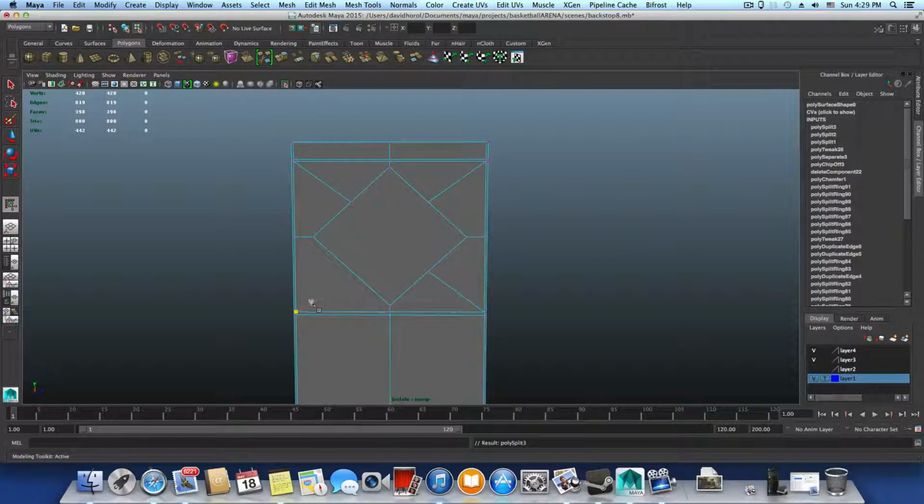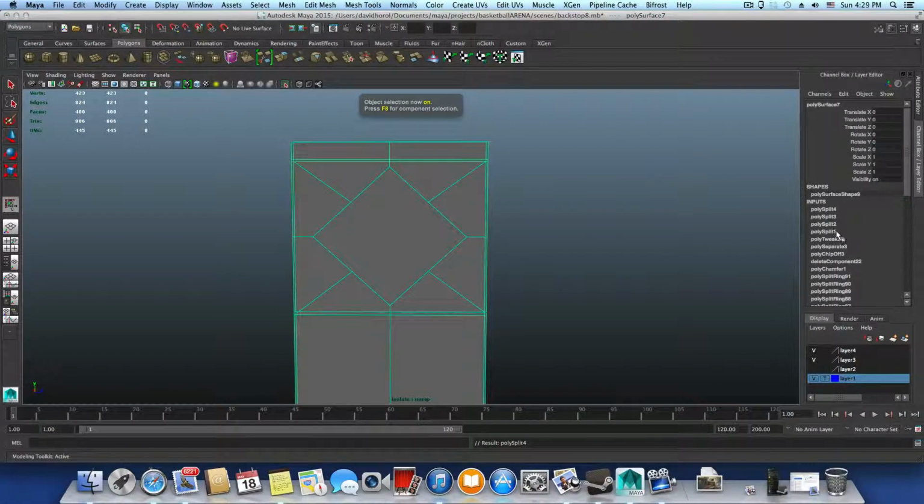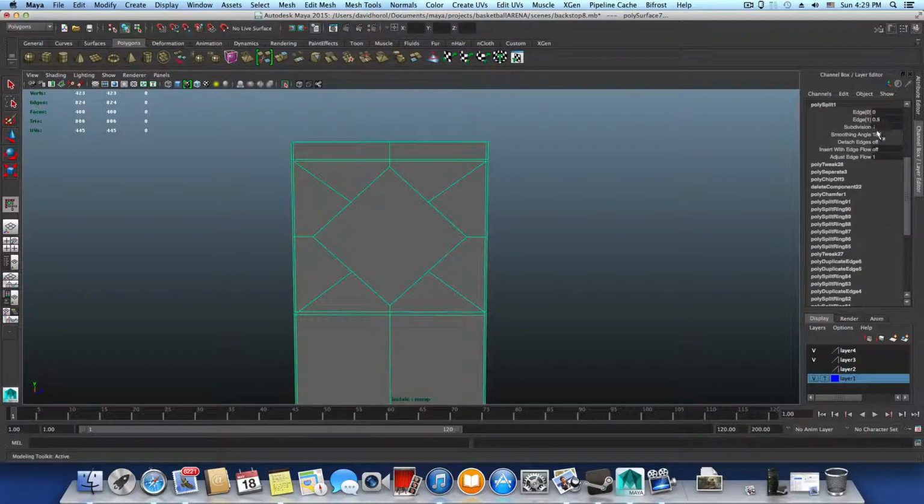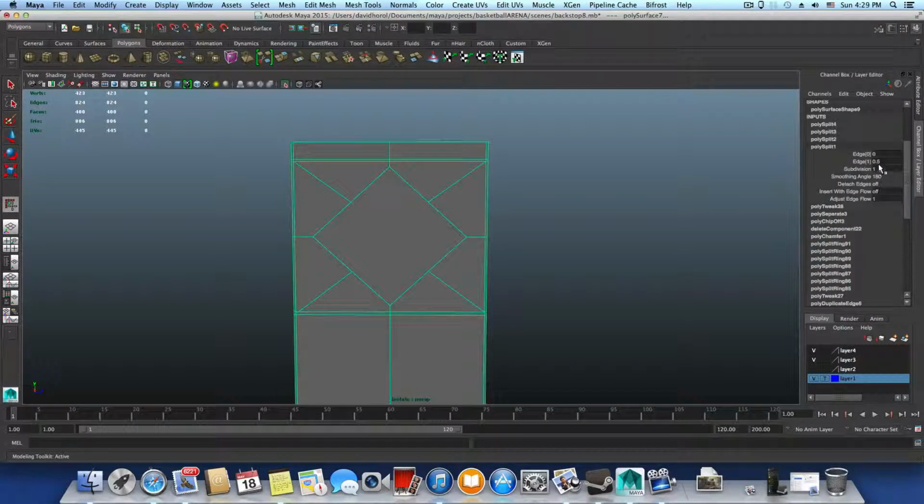Okay, so I will click, second click, hold, drag, find the 50, release, right click, and make it permanent. So you have 4 here. I will press F8, bring in this polysplit. This one is already set to 0.5. See, 0.5, that's okay.